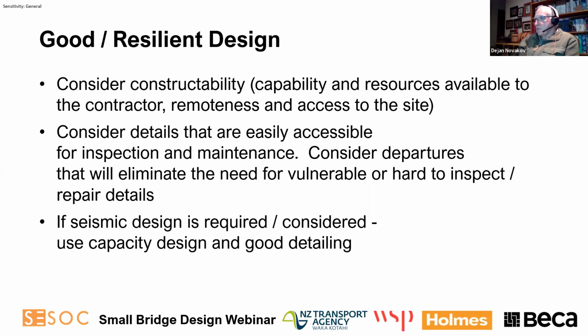If you have a single span small bridge, which is well confined with abutments and generous seating, which will prevent unseating, then you probably can go without the linkage bars, which are typically difficult to inspect. They are prone to damage, and they are almost impossible to replace. So if seismic design is required, consider using capacity design and good detailing.